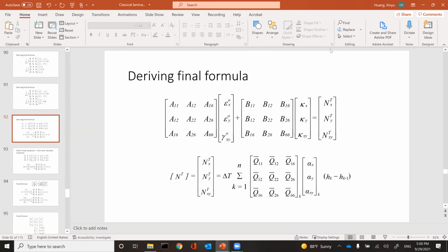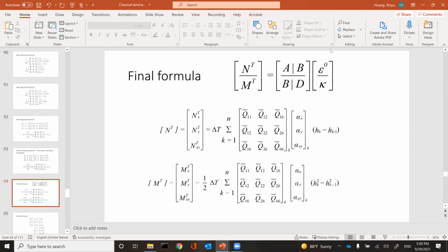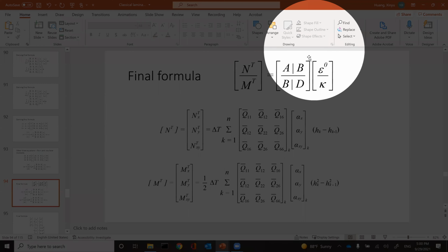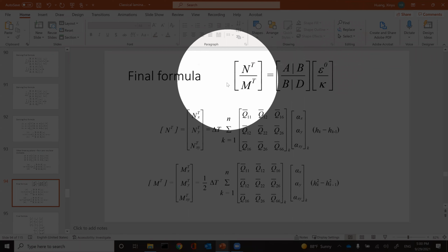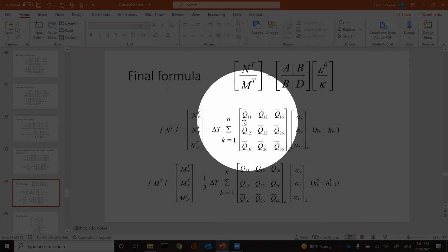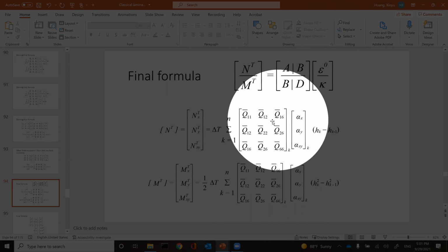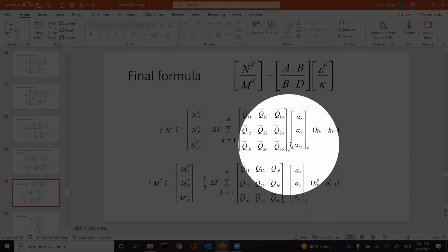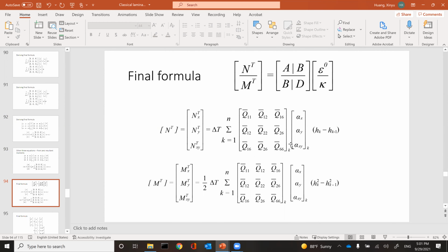All right, so once you have the code, you see that the calculation is very similar to the ABD calculation for internal stress effect. The only difference is you calculate this 6x1 vector using these equations. These are not the true load. These are the hypothetical load due to thermal effect. You don't apply this load. These came out of the derivation. The condition we apply to get this is the zero moment and zero force condition, because we take the panel out and didn't apply any force or moment. The total load is zero.